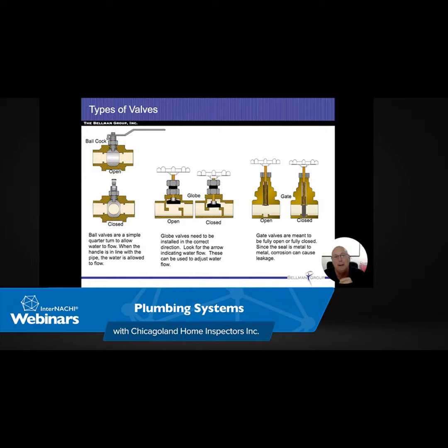PVC and CPVC, they're both plastic. They're both designed for potable water. Excuse me. I like to remember the term potable. Somebody from the military said that's exactly where the word came from: you're able to put it in a pot, but it means drinkable. Both of these pipes are for potable water. The only difference between the two of them is what temperature they're rated at.